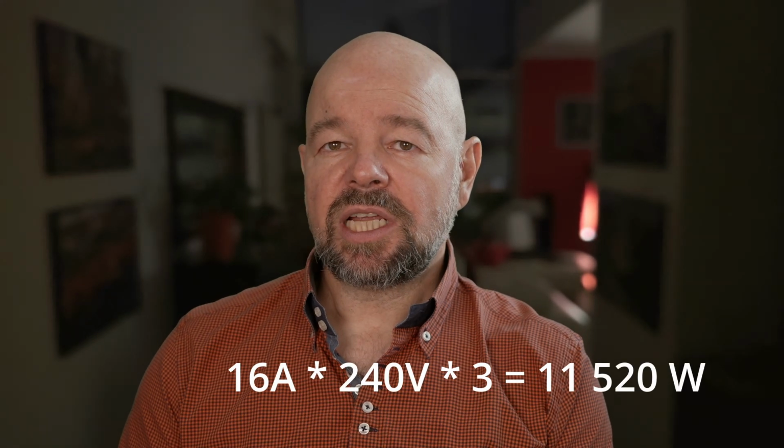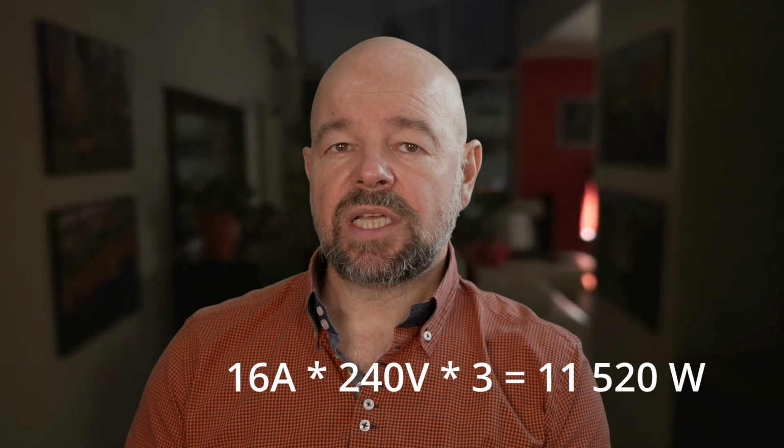It uses 16 amperes per phase maximum, and my house is connected with 25 ampere circuit breakers, so it works fine with our existing connection to the grid. If I wanted a faster charger, 22 kilowatts, if my car supported that, I'd need to upgrade the circuit breakers, and it would increase our monthly bill fixed fees, which are now a bigger part of what we pay, since most of the consumption is covered from the solar panels. The fixed fees are fixed.